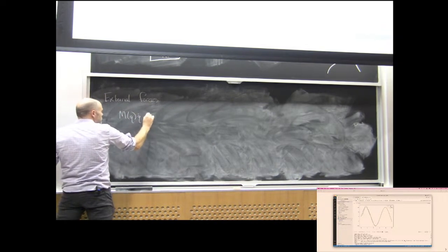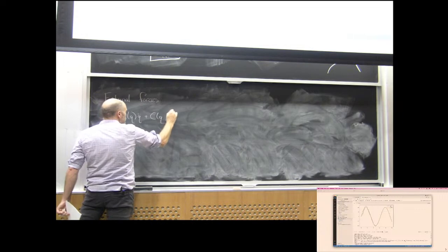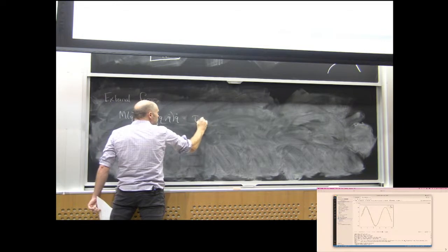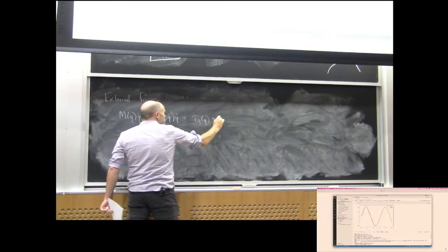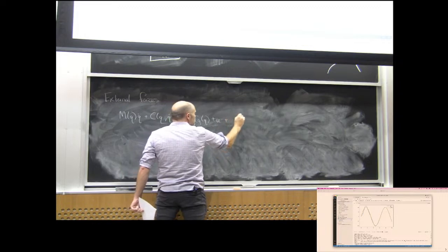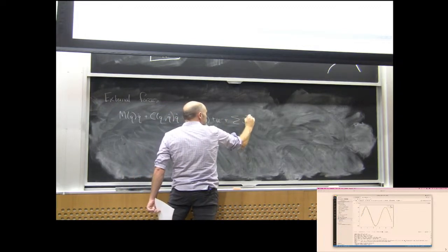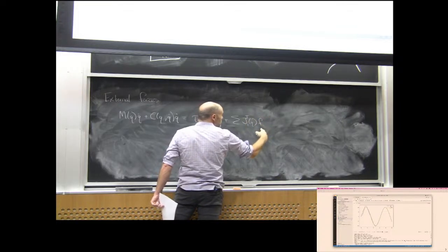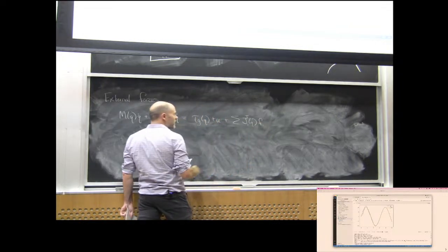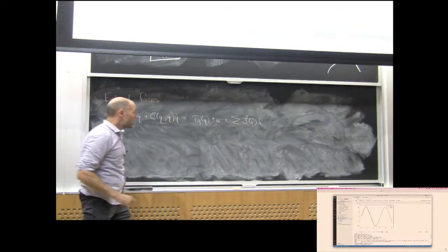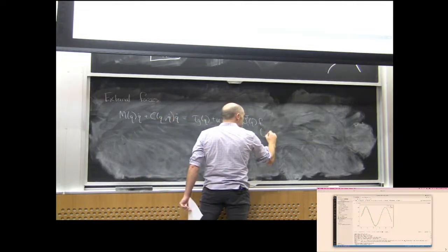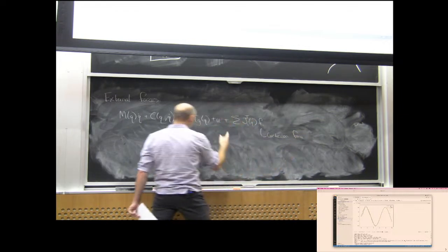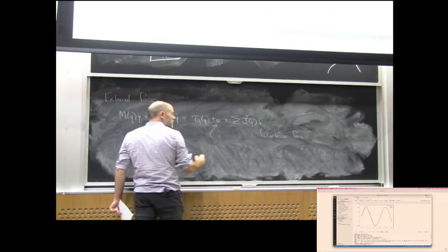I showed you once before when we were talking about friction cones and whatever, I showed you these equations without fully justifying them. The way that forces enter the multibody equations, I wrote this down sort of quickly without justification, that it looks something like this, yeah? That I have a Jacobian transpose times F, where this is a Cartesian force. But these equations live in joint coordinates, right?